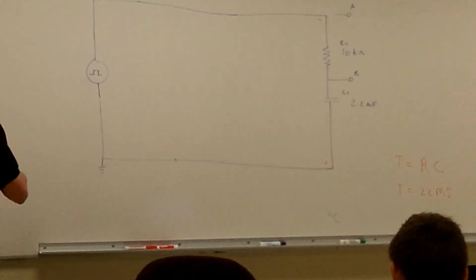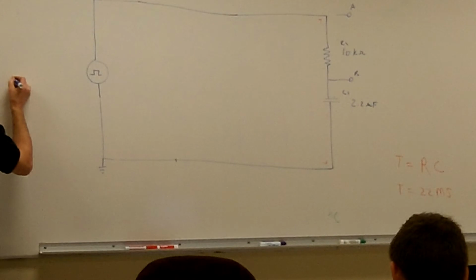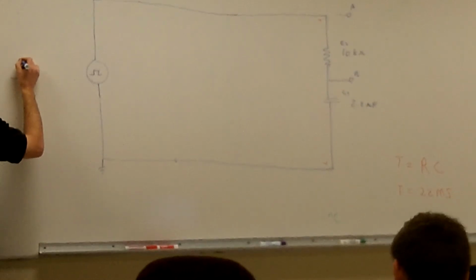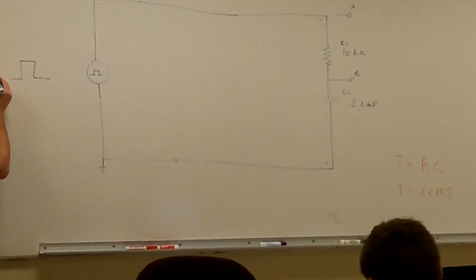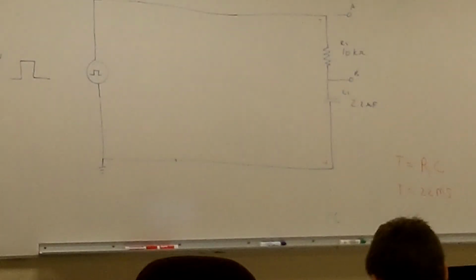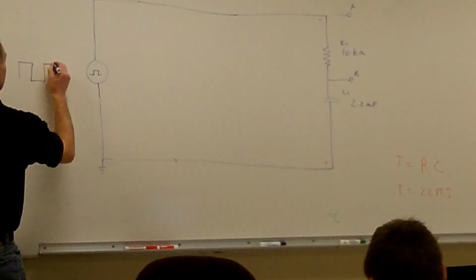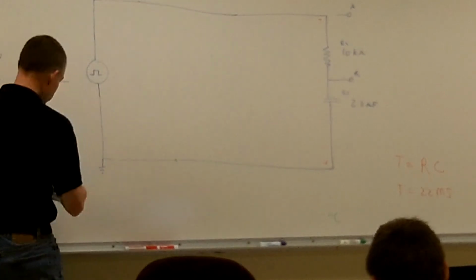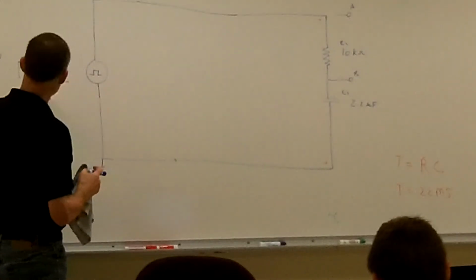Now when we're putting in a square wave, and we're working with a circuit like this, typically when we're working with square waves or pulses, for most applications, we're going to have that DC offset in there. So what we want is for our square wave to have a DC reference of 0 volts, and then go up to plus 10 volts. Draw 2 waveforms here.